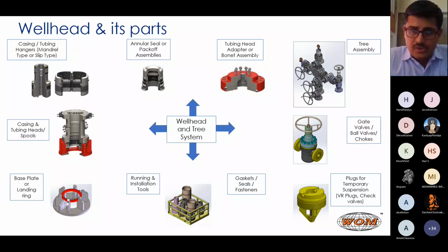A wear bushing, like during the drilling phase, when you are running the drill bit into the wellhead, there is a possibility that it can damage the wellhead internals. To protect that, you install the wear bushing or a bore protector. Okay, during only the drilling stage. Once the drilling is completed, you can take it out.